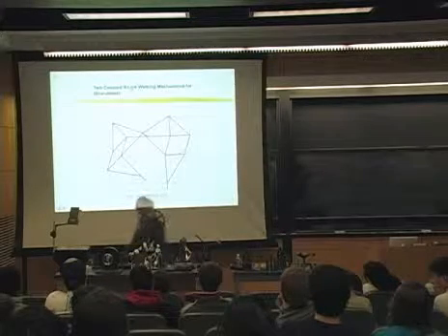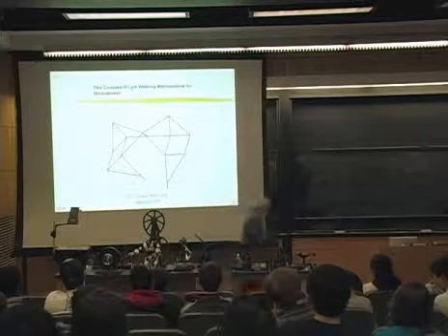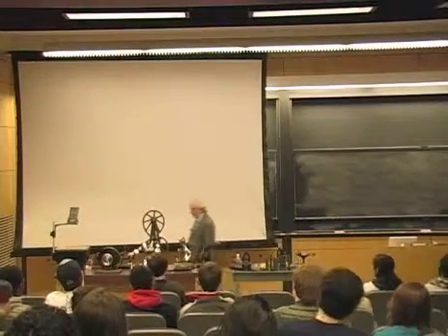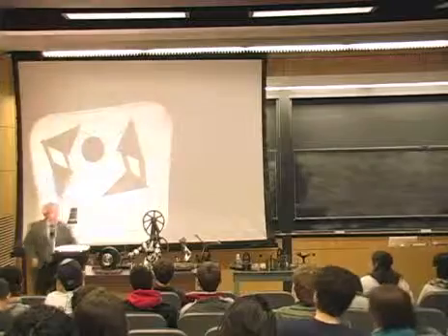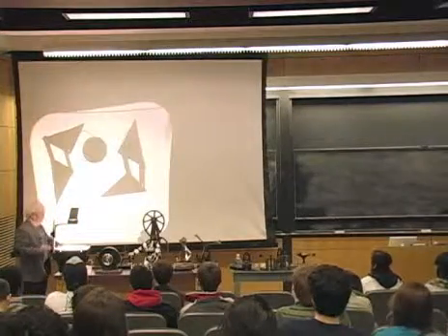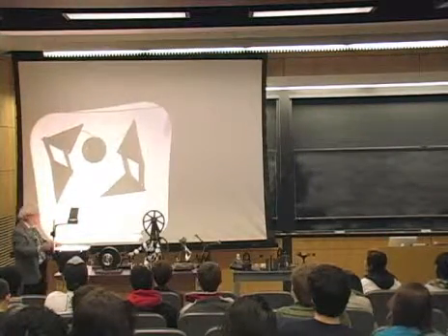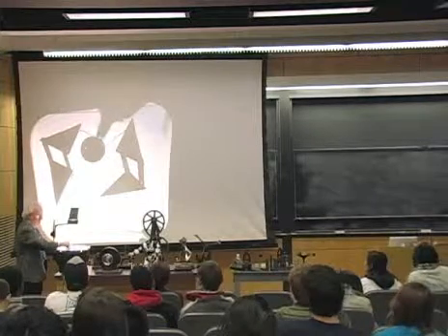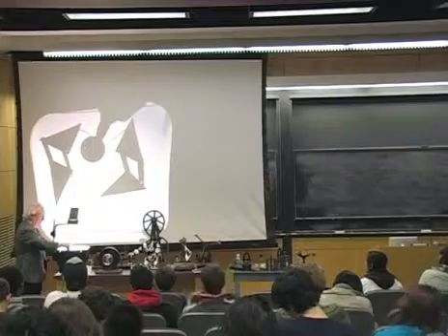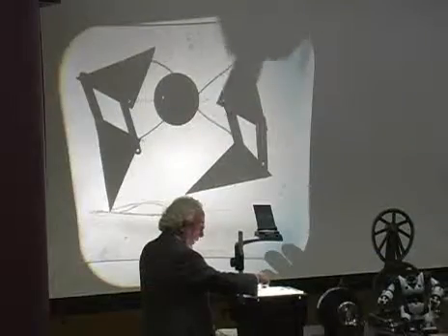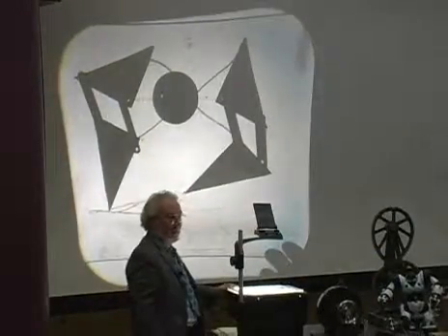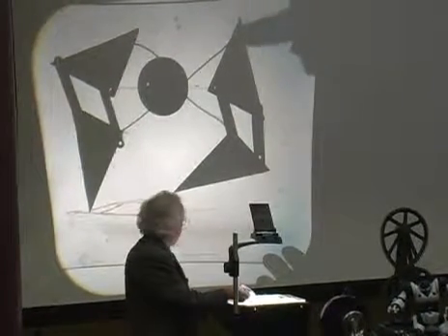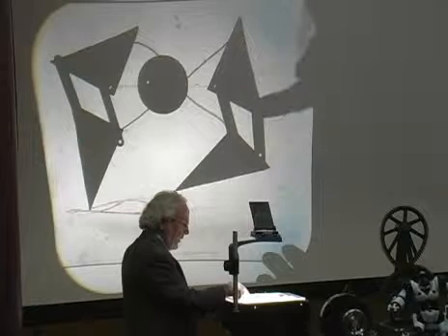And in fact, we can create a little toy walking mechanism here. So you can see now the 2 legs here. And the 8 links involved, first of all, the base is 1, then there's the crank here. That's 2, 3, 4, 5, 6, 7, 8. All right? And some of these links have more than one joint. For example, this one here has 1, 2, 3 joints.